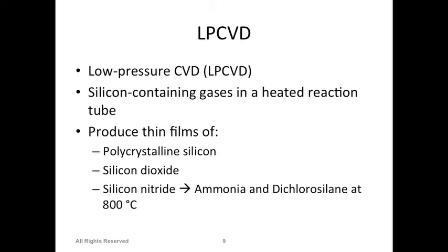Now the question is, if we have a metal on the surface. There may be some situations where we have a metal on the surface and we want to deposit, let's say, silicon nitride with the LPCVD process, and the temperature required for that is, let's say, about 800 degrees centigrade. Metals normally do not have very high melting temperatures compared to insulators. For example, aluminum is about 600 degrees centigrade, okay, 660.